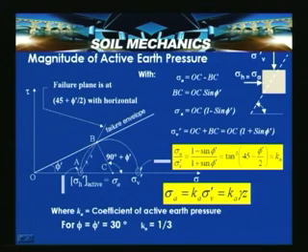The Mohr circle intersects the sigma axis at A, touches the failure envelope at point B, and has its center at point C. From the geometry, we can say that sigma A is equal to OC minus BC. Sigma A, which is this one, is nothing but OC minus BC, which is this distance. But from the triangle OBC, we can see that BC is equal to OC sin phi dash.